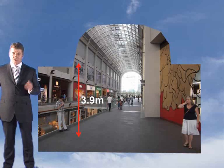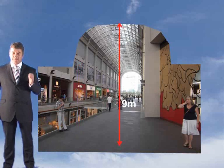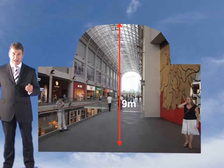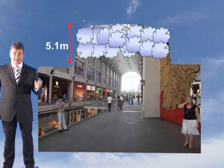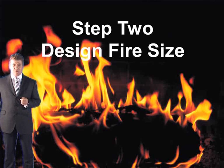Remember for later as well that the height to the ventilators is 9 metres, so the depth of your smoke layer is 5.1 metres. You will need that for later on, so remember that. So that's the clear lay height, and that's step 1, the design objectives, what we know we need to achieve. Let's move on to step 2 then.